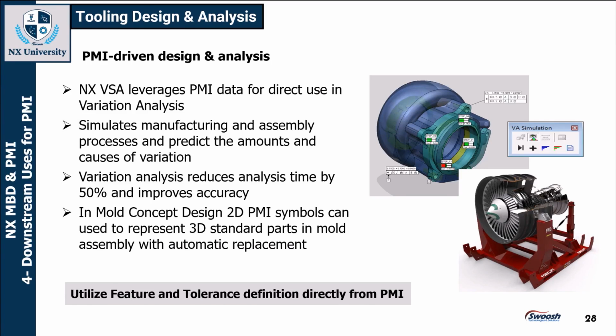And mold concept design, 2D PMI symbols can be used to represent 3D standard parts and mold assembly with automatic placement here. We can utilize feature and tolerance definition directly from the PMI that's embedded on the part to quickly generate these VSA reports and do these variational analysis and stack up analyses on our designs.